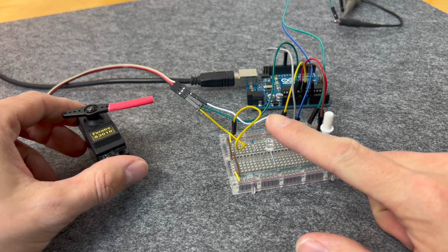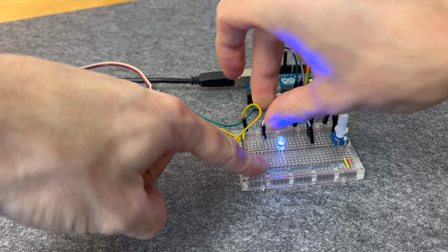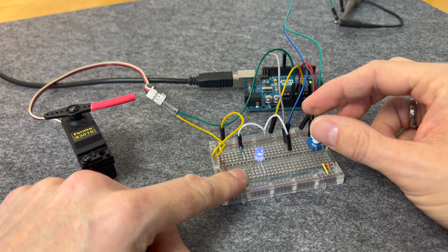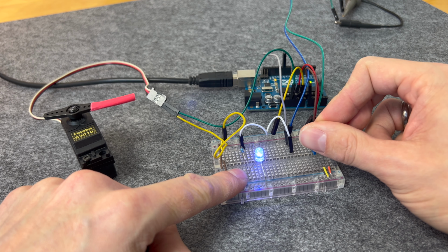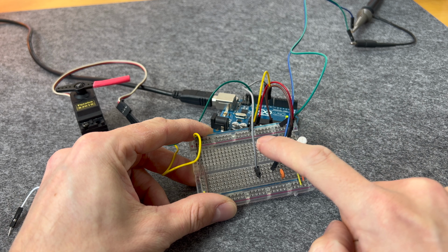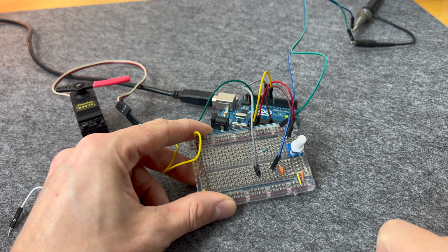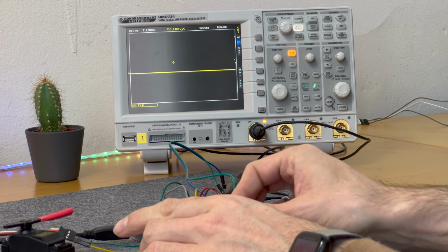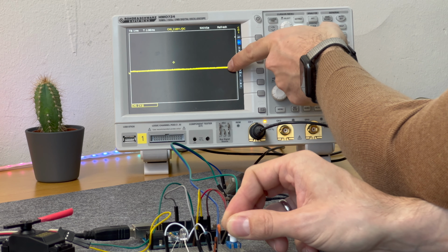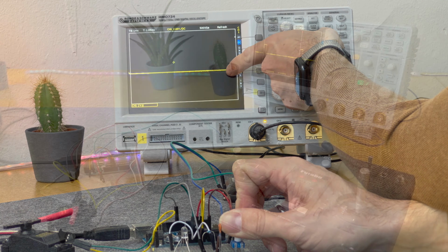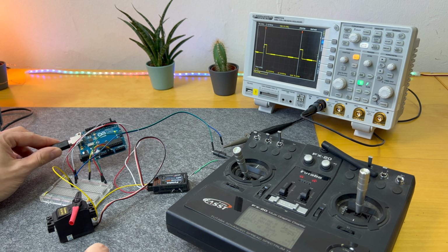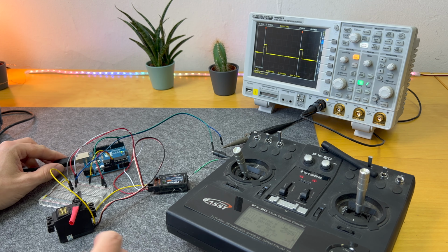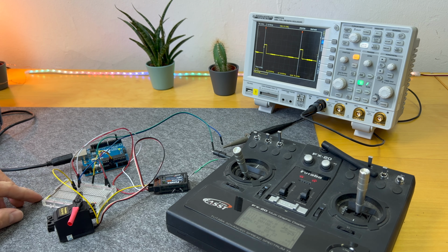Instead of this servo here, we could also connect an LED to this pin. If we now rotate the potentiometer, we can see that the LED dims down and up depending on the duty cycle of the PWM. If we add a hardware low-pass filter, so just an RC circuit here, the digital value can also be transferred into an analog value. That's pretty sweet and does not even require a dedicated digital to analog converter. So after changing the code to timers, we are free to do something else with the microcontroller. What can we do? Well, let's actually read a PWM value which comes from another module.